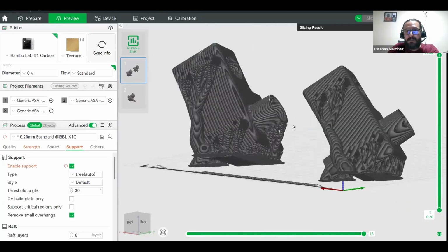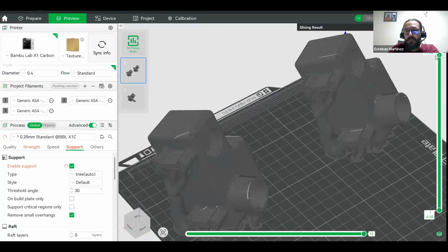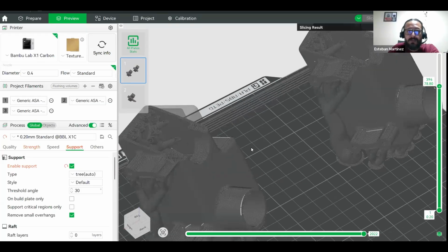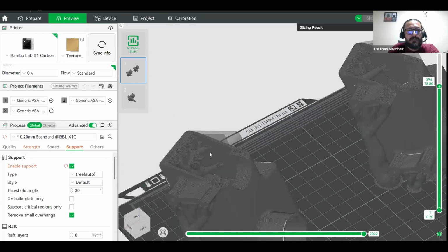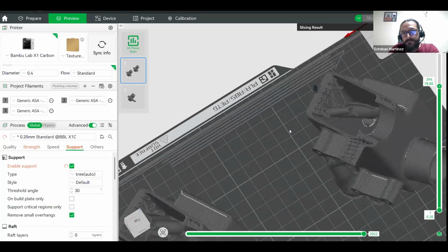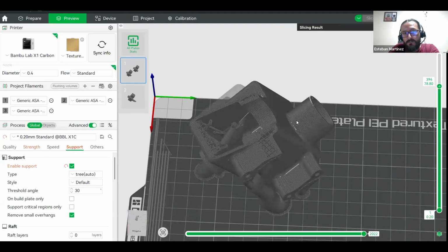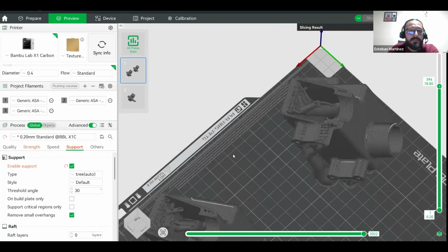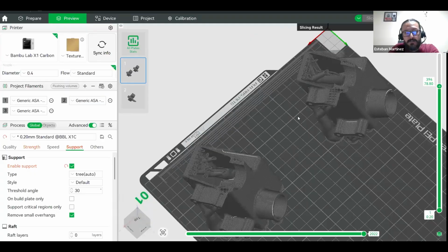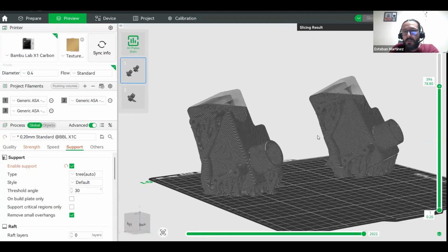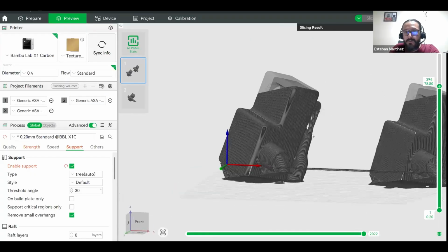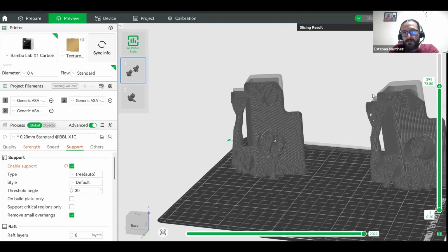The other aspect, which I found okay at the beginning, but after doing it, it was not that fine, is the internal supports. As you can see, 3D printing supports internally, tree type. I was able to remove them at the end due to the big holes that we have available along the part, these 3 holes.